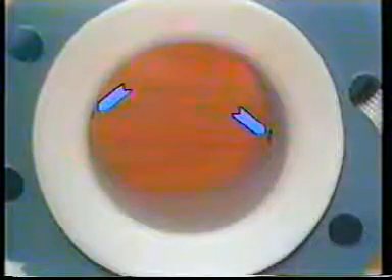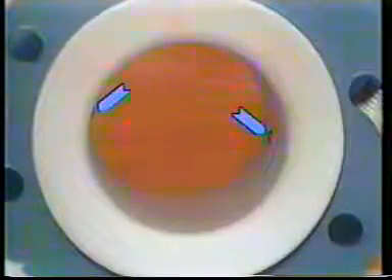In order to serve as a conductor, the flowing fluid must have an electrical conductivity. The voltage induced into the flowing fluid is measured by two electrodes projecting through the metering tube liner. The millivoltage measured by the electrodes is directly proportional to the average flow velocity, and thus to the volumetric flow rate of the liquid passing through the meter.